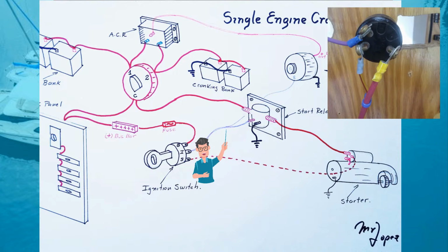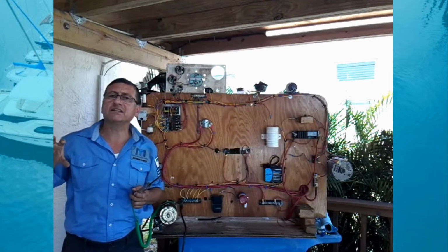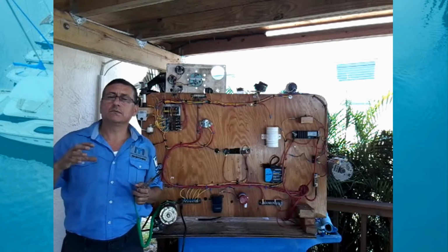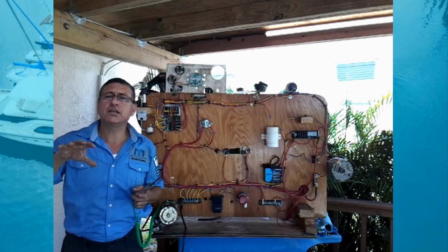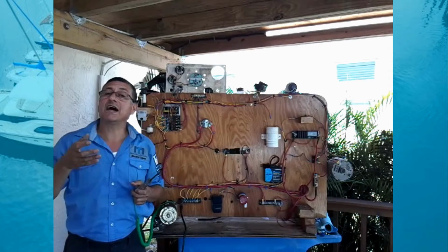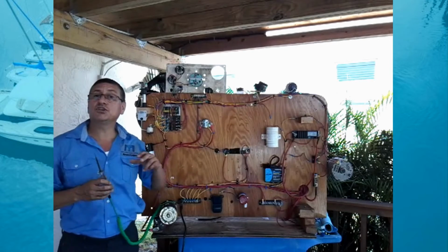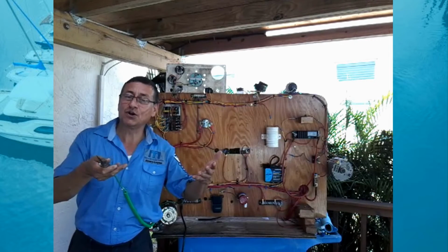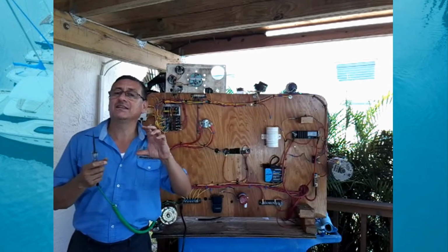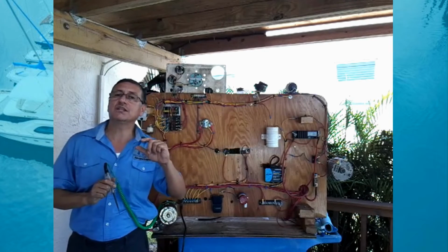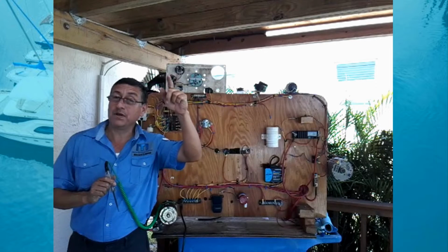In that position, you hear that some equipment is activated: the lights on the board, the radio, the fuel pump, and other equipment. Those are activated because the ignition switch sends the signal and some relays close or open, depending on whether the relay is normally open or normally closed, depending on whether the relay is used in the 87A output or in the 87 output.